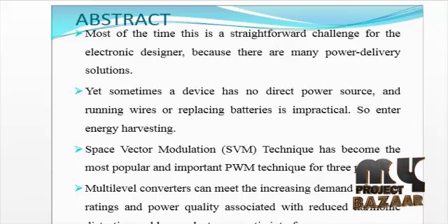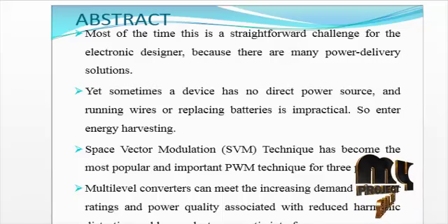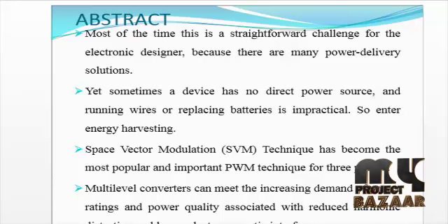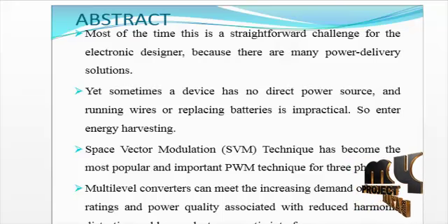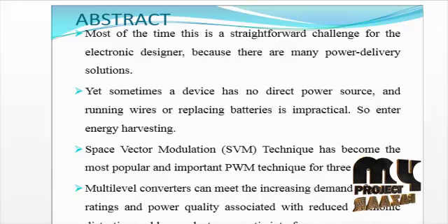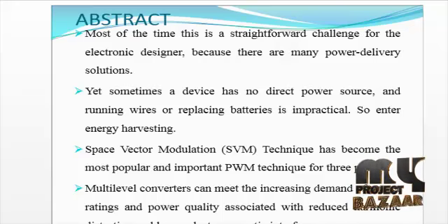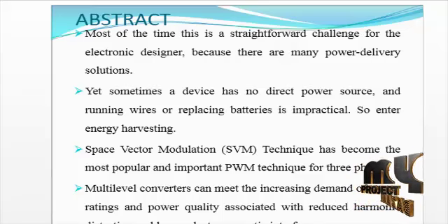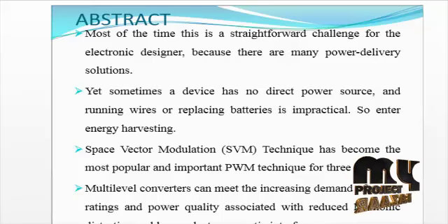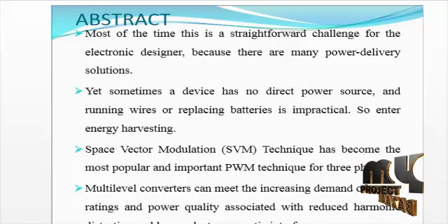In this process, only a diode is added in front of the original topology to block the leakage current loop during the active vectors and open zero vectors. The pulse width modulation (PWM) technique is applied with one leg shoot-through zero vectors in order to reduce the leakage current through the conduction path during the change from and to open zero vectors.